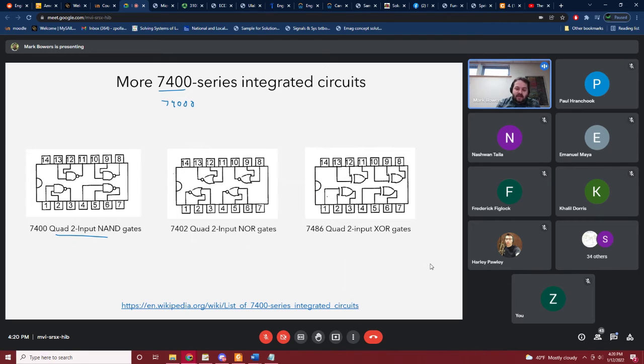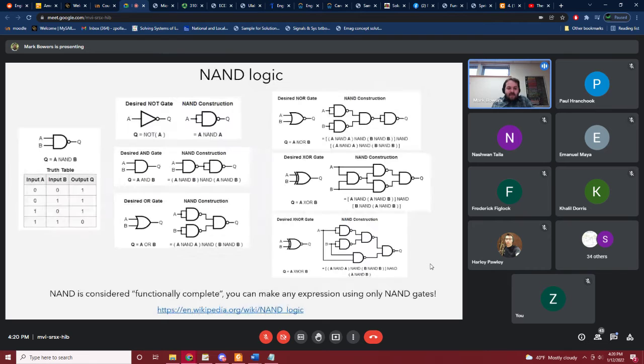One thing that's interesting here, arrived at through all those identities and the Boolean algebra theory, is that NAND is a universal gate, and you can make any kind of gate just by wiring together a bunch of NAND gates. So for example, if all you have is NAND gates, you're stuck on a desert island with NAND gates, you can make any kind of gate.